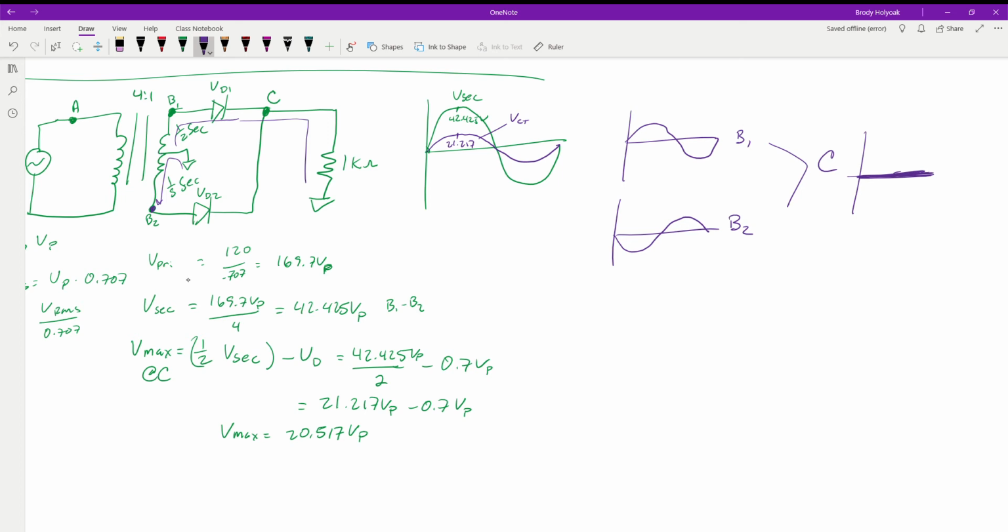But since we put a diode in here, at each of the positive cycles of the waveforms, it's going to put the diode in forward bias mode, which means it's going to drop 0.7 volts. But when it gets reverse biased, it's going to clip off the signal. So what we have here is two clipping circuits. We have one treating the original waveform, then we have the second one, which is 180 degrees out of phase of the first, which is something we learned when we were playing with the transformers the first time.